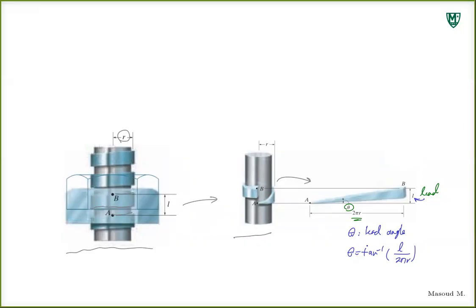Now, when we have this screw inside, let's say, a piece of material or a part in a system, or we have a bolt around it, there are going to be two surfaces in touch with each other. You have the thread from the screw and then you have the surface from the bolt. Now, depending on this lead angle, the lead, and the moment you apply to the screw, you can have 4 possible cases.